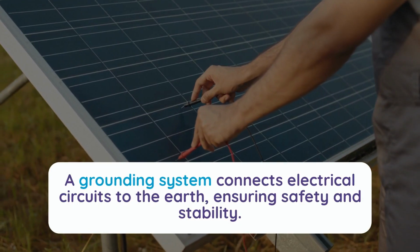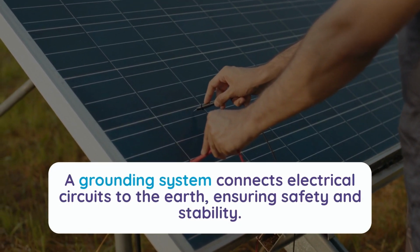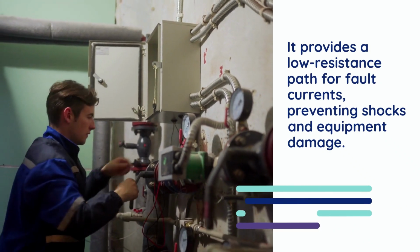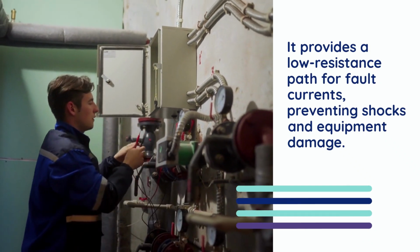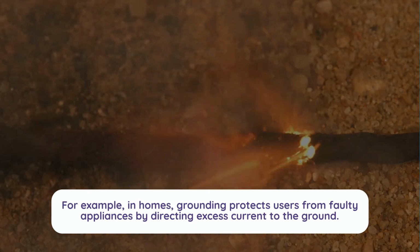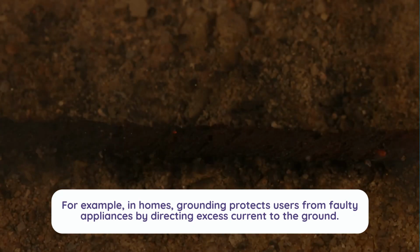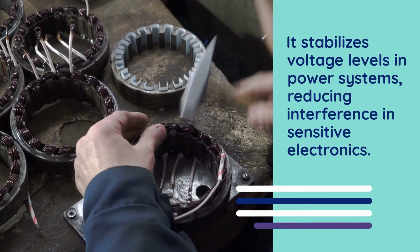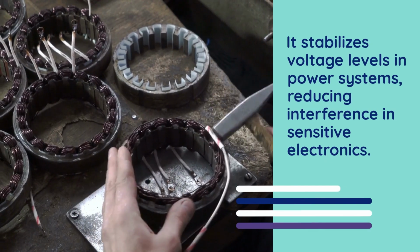16. What is the purpose of a grounding system? A grounding system connects electrical circuits to the earth, ensuring safety and stability. It provides a low-resistance path for fault currents, preventing shocks and equipment damage. For example, in homes, grounding protects users from faulty appliances by directing excess current to the ground. It stabilizes voltage levels in power systems, reducing interference in sensitive electronics.